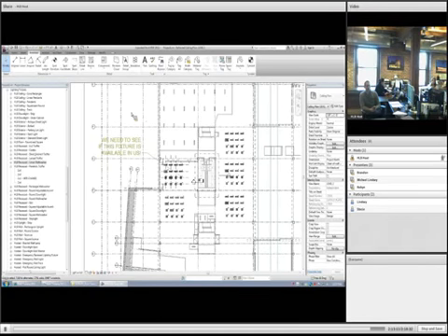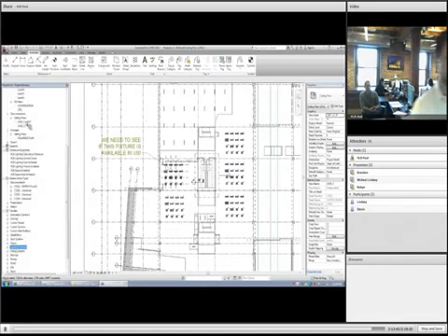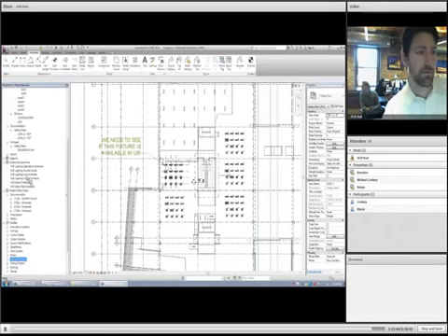Cool thing for spaces for you all is that we can set the space type and what the power density budget is for that space type, for that room type. We can do things like the required lumens, or required illuminance, and we can immediately tell if we're meeting that or not. The code, if there's a code required or an optimal, we can set all of that. You're going to see some of those parameters.